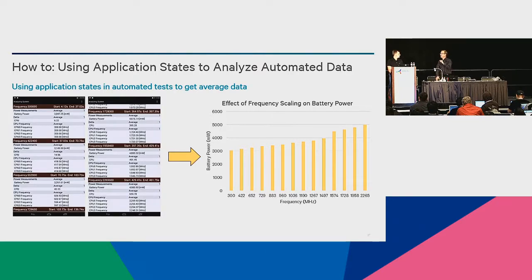I want to comment on that. Yeah, you understand the question. I do. If you were paying attention earlier, I showed you the one chart where the one app was running the processor at 100% and was using 4.3 watts of power, which is a crazy amount of power. There are several different options you have. One is, in that particular case, the GPU was basically idle. So anytime you can offload from CPU to GPU, it's going to make a difference in power.